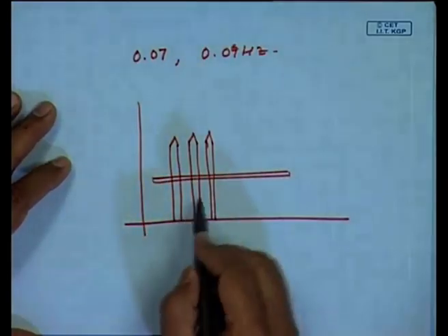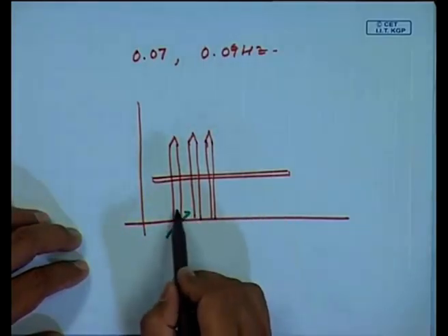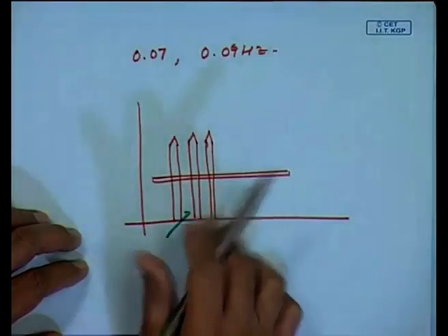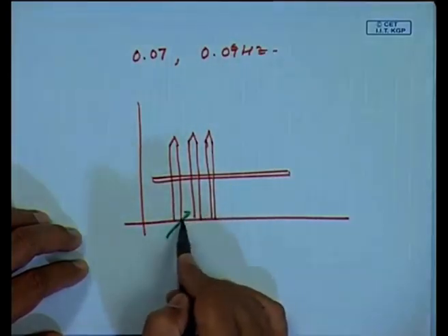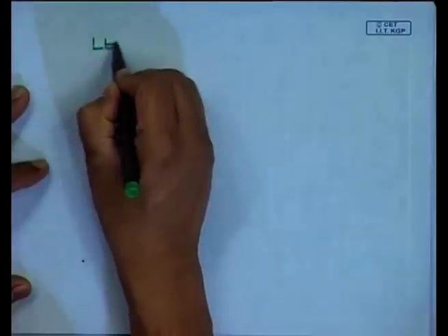So, if I was to hit a cricket ball, the cricket ball will pass if these fences are wide apart, if these pegs are wide apart, but I will catch it if they are close by. So, this is what is known as the picket fence effect in FFT. Once we have a finer resolution, we are going to catch the signal. So, this is to be avoided by having adequate frequency resolution by increasing the number of data points.